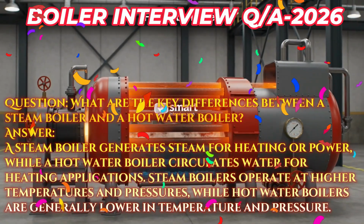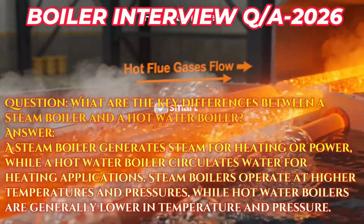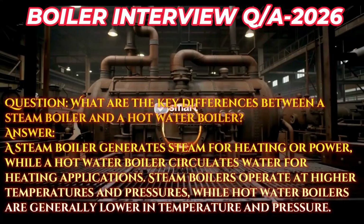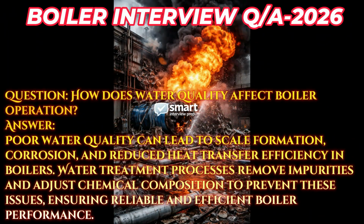Answer. A steam boiler generates steam for heating or power, while a hot water boiler circulates water for heating applications. Steam boilers operate at higher temperatures and pressures, while hot water boilers are generally lower in temperature and pressure. Question. How does water quality affect boiler operation?